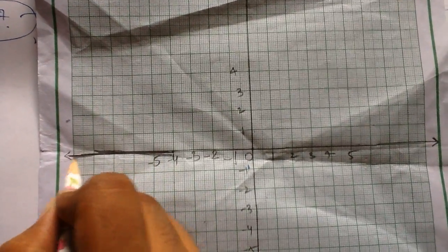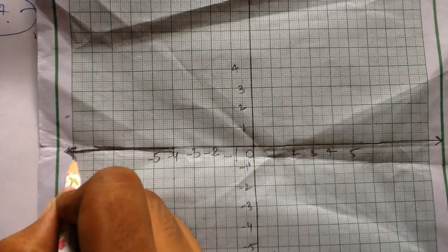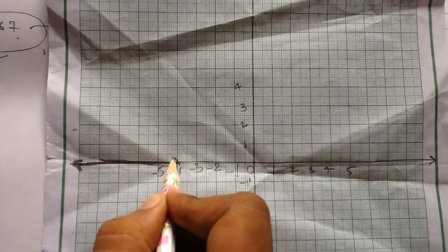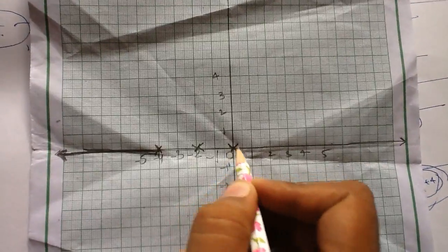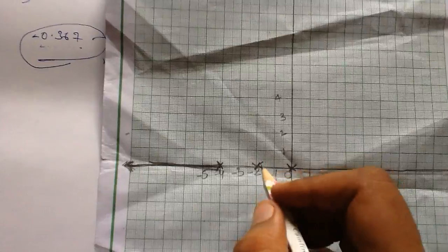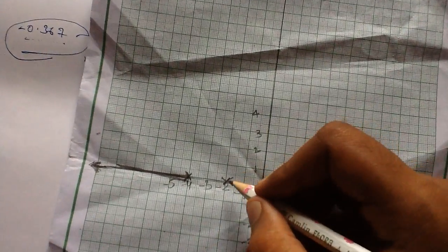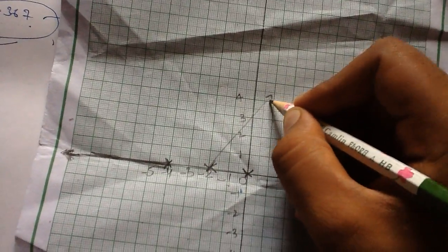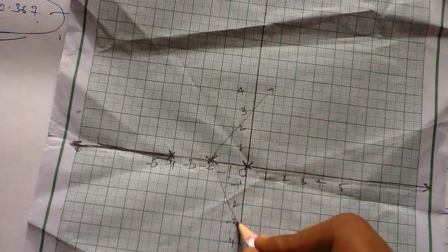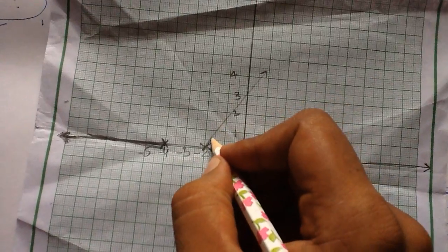So that is the first part of the root locus. From minus 4, which is a pole, minus 2 is a pole, 0 is a pole. From minus 4 it's going to infinity, so darken that. Now you have asymptotes at 60 degrees. Please use a protractor. I am not using a protractor. 60 degrees and minus 60 degrees.